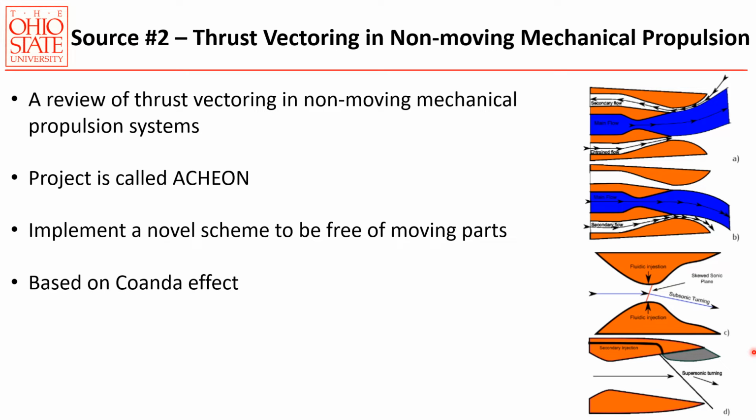Another concept is based on shock vector control. By injecting a secondary control flow into the throat of a diverging section of the nozzle, in this case the formation of the flow is modified by a certain angle, since the secondary injection creates a virtual pressure ramp affecting the main flow. The main flow is deflected due to the orientation of the oblique shock. To obtain maximum deflection, we must ensure that the shock does not impinge on the opposite nozzle wall, since in case the flow impacts on the wall, it will be reflected, thus compromising the system.